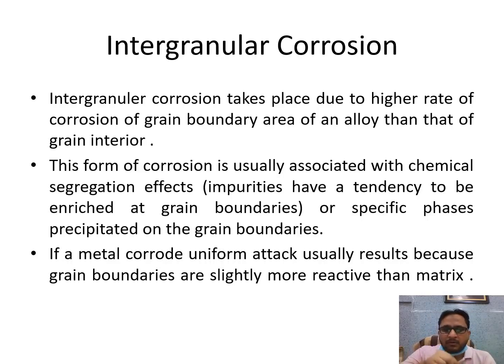So at the grain boundaries, because chromium is present in a higher percentage and it is anodic, it starts releasing electrons and undergoing corrosion, leaving the grain centers protected, while the boundaries between the grains start corroding.